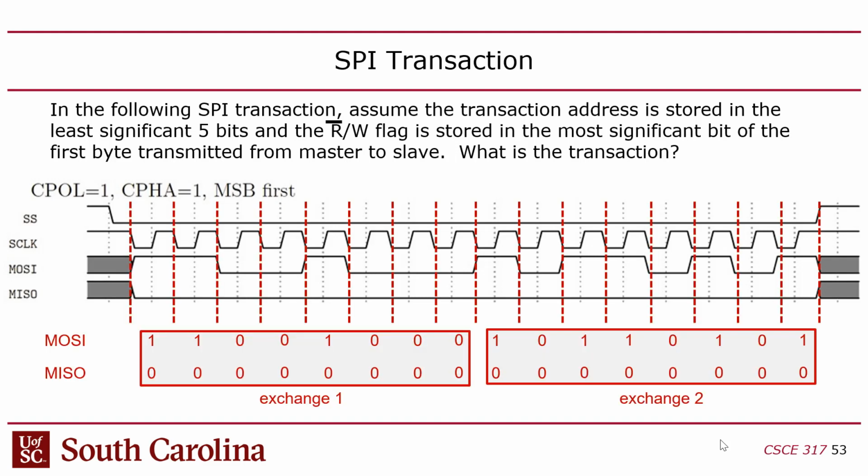So what I've done here is annotated this. I put my dotted lines to denote the beginning and end of each bit slot. So my dotted lines are indicating when the data bits are changing. So when you read the values, you're reading between these 2 dotted lines, whereas on this timing diagram, they have additional dotted lines that show the read points, right?